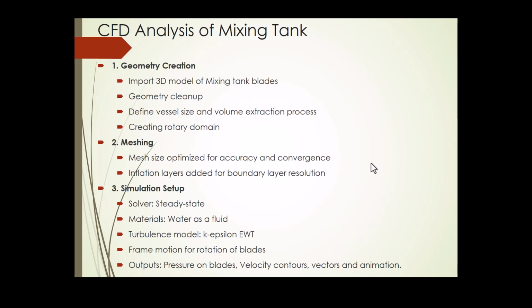So today we are going to perform CFD analysis of a mixing tank. So what we will be doing is, first of all, this first step is geometry creation. We'll be importing a 3D model of the tank blades and we will be easing up the geometry. We can say we are cleaning up the geometry for our own use. Then we will be defining one vessel size and we will be extracting the volume from that vessel.